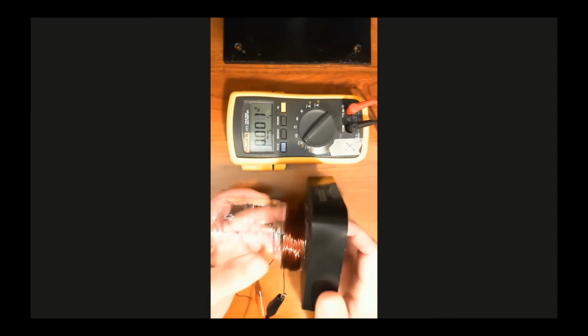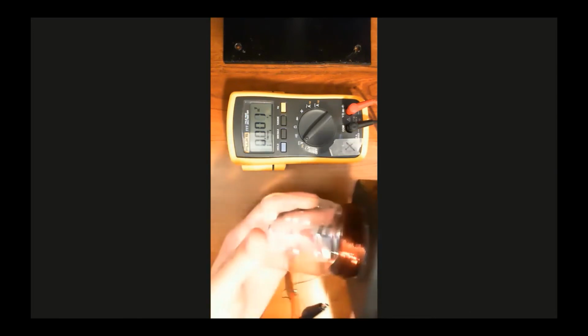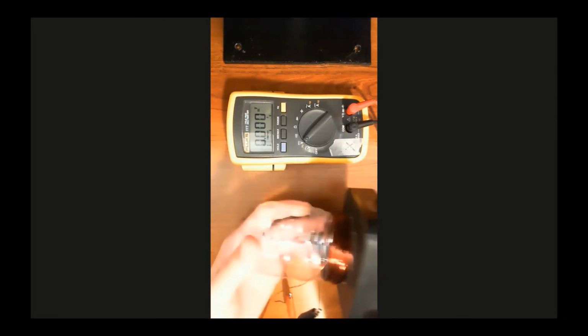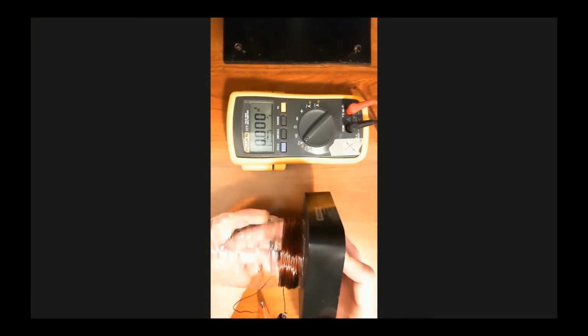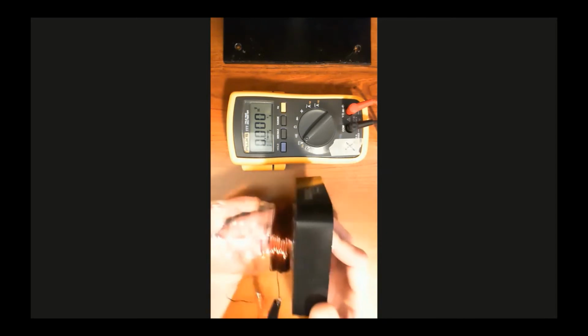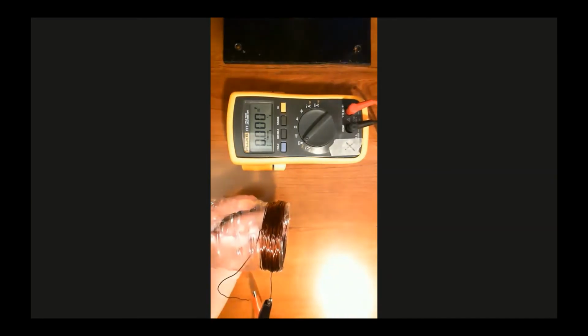voltage. Notice I can't just say that I have motion, because now I've got motion, right? I'm moving both of them, and I really don't have an induced voltage, right? There might be a few very tiny fluctuations, but there's really no induced voltage here when I'm moving both of them. I have to move one of them relative to the other in order to get an induced voltage.